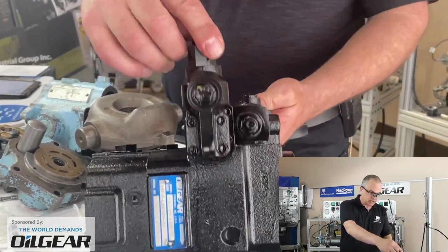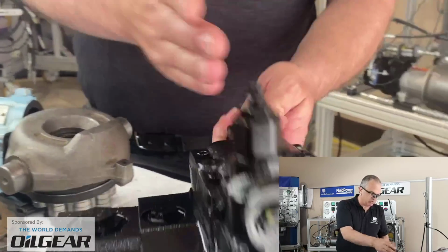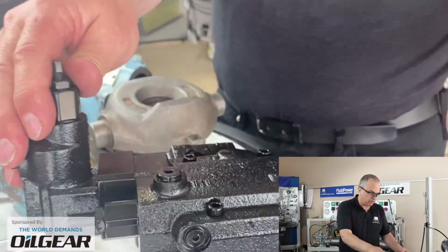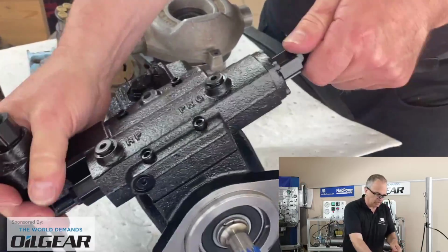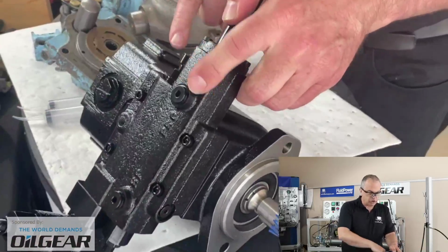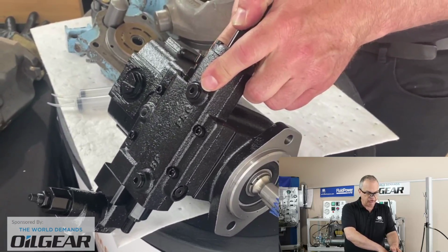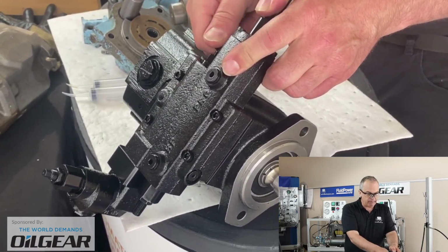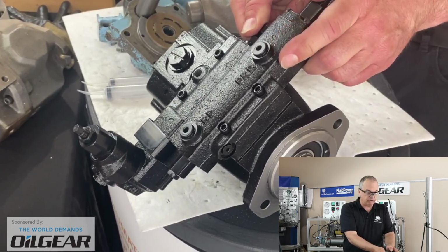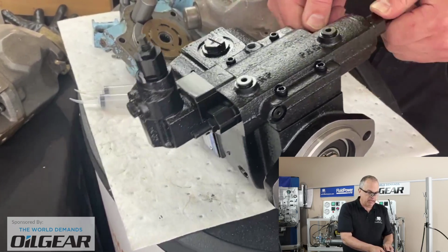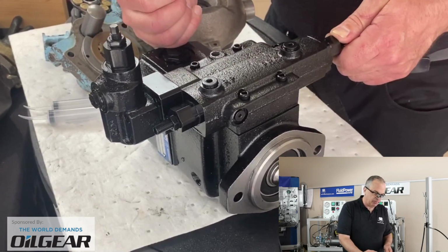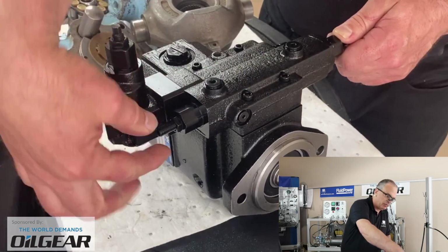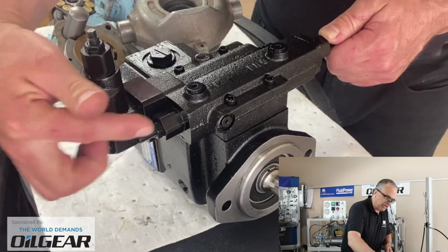Okay, this particular pump, with all of the transverse, we bought it configured with about as many controls as you can ever get all combined at the same time. So the pressure compensate adjustment is sitting here. This is the adjustment for the maximum cutoff pressure. That's the one we've been talking about the most. And then the maximum volume stop, meaning how large can we allow this pump to be, or do we need to shrink it down from its maximum? That's this adjustment screw over here.